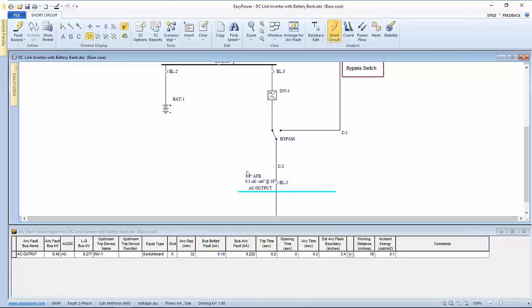And a keen eye observer like Street might suggest that something fishy is going on, and he'd be right. It turns out this is quite literally a function of the IEEE model and the nonlinearity, or conservative values that you get when you're on the low voltage side, less than 240 volts of AC calculations. So I just invite you to keep an eye out for that.